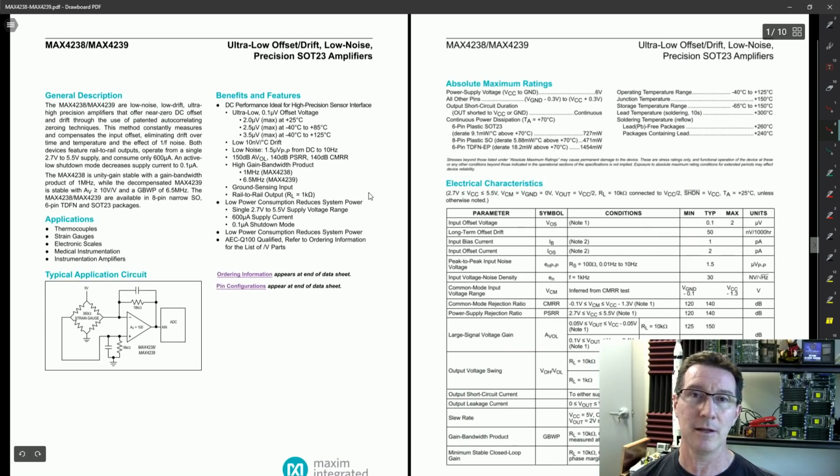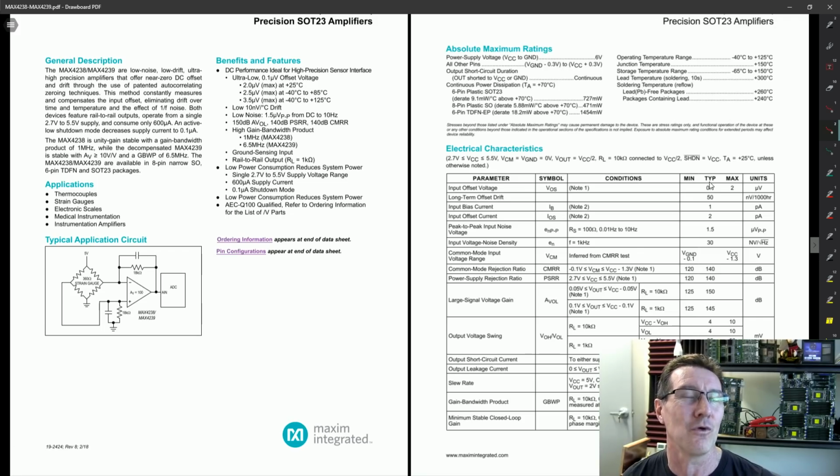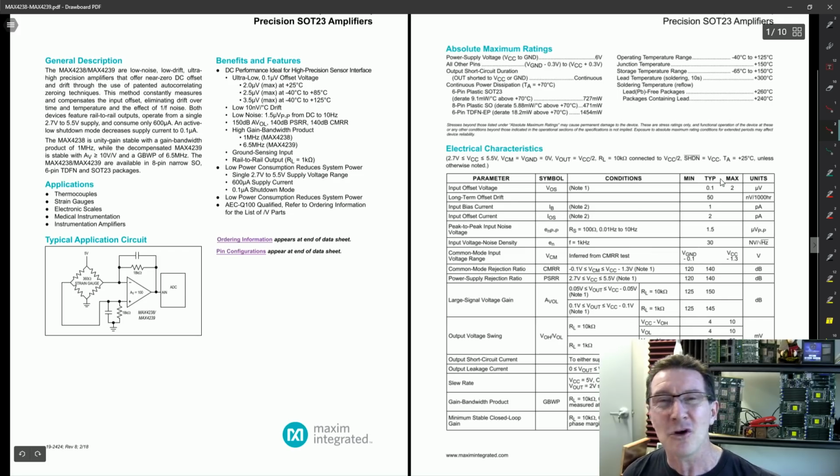Anyway, we're like 10-15 minutes into this and we haven't even started looking for alternatives yet. Let's just say that we're looking for, by the order of, which typically means order of magnitude, but we want to be a bit tighter than that. Not as tight as a nun's nasty, but reasonably tight. So, 0.1 microvolts-ish offset voltage is what we're shooting for.